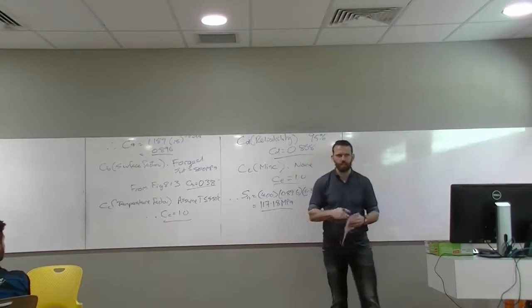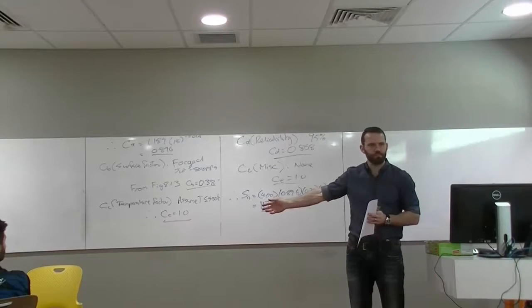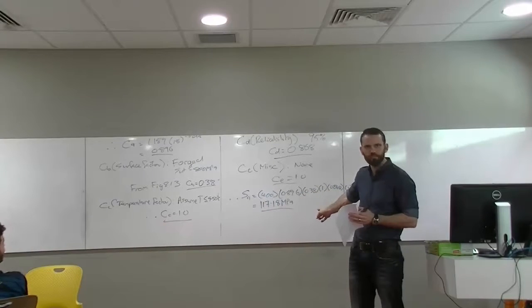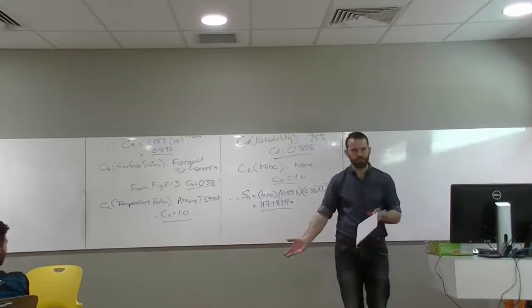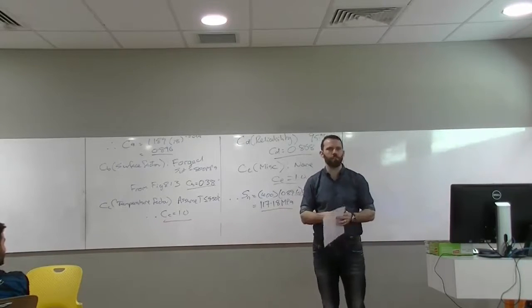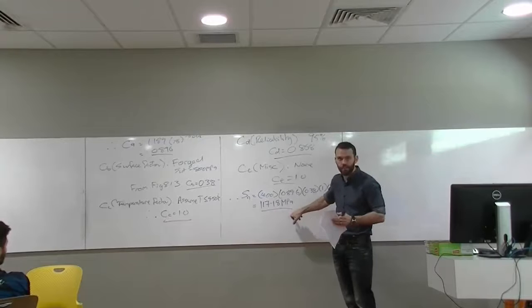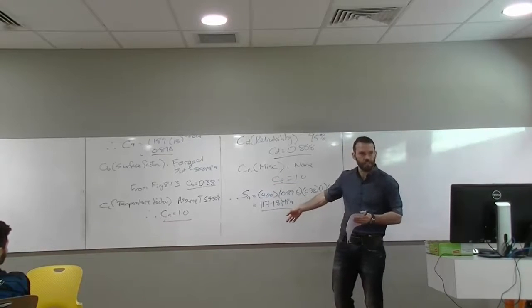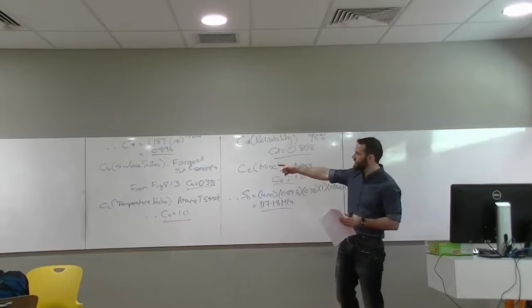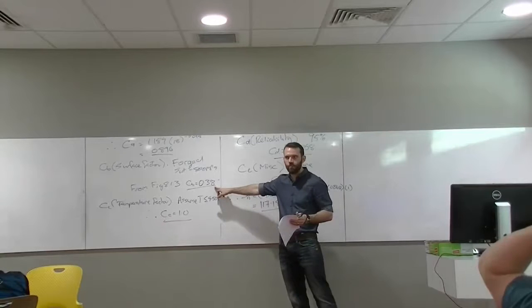Alright, so let's look at that for a second. We started with 800 megapascals, and look where we've got. Really big difference. 800 megapascals is probably 400 megapascal yield stress, or maybe 500 for a material like that, and we're a lot under that. We've only included a bit of reliability and a bit of change for surface, and this isn't even including a factor of safety yet. So as forged, it's terrible, and we might want to deal with that.